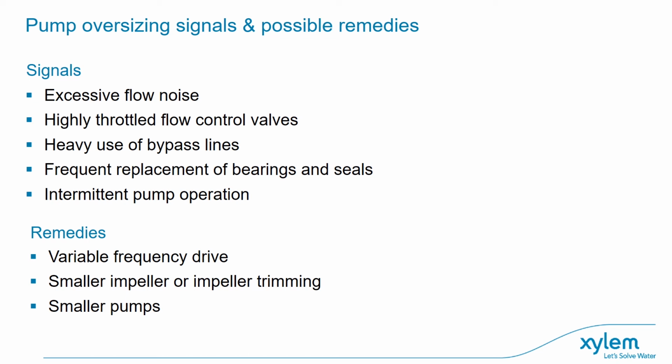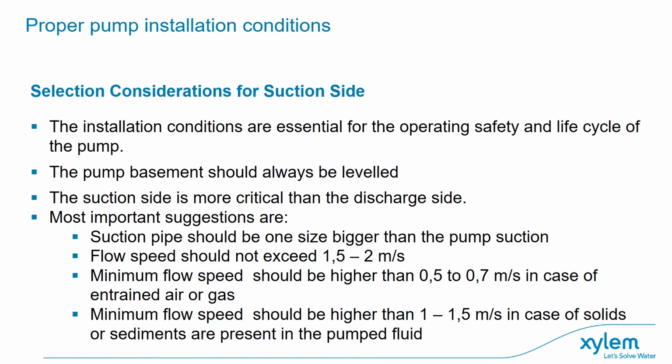Last but not least is the possibility to think about a smaller pump or a booster set which might couple more than one pump, one duty and one standby each time, and occasionally working together in the period of peak performance required.